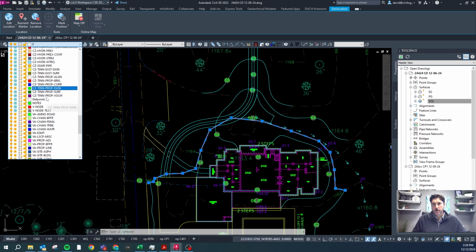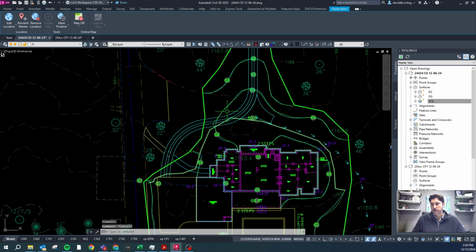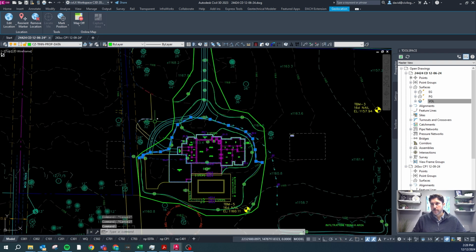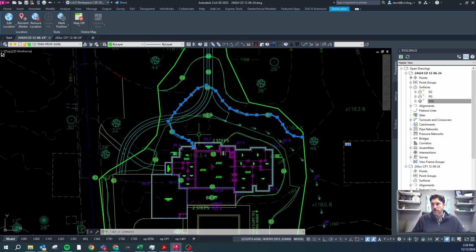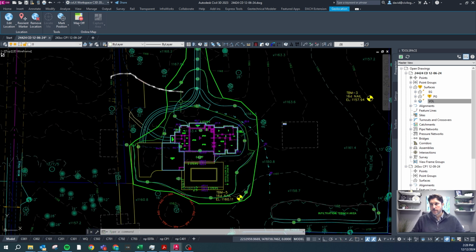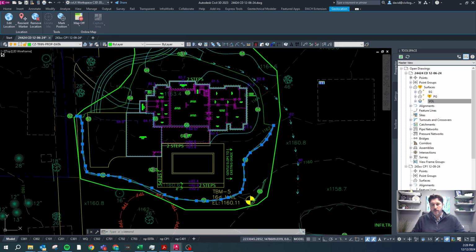You're normally not going to do this. I'm just doing that on this project because of these splines. Normally you're just going to keep them on your standard contour label. Elevation 1162, and so now we'll delete this one, and that one, and that one. That 60 can stay the same.